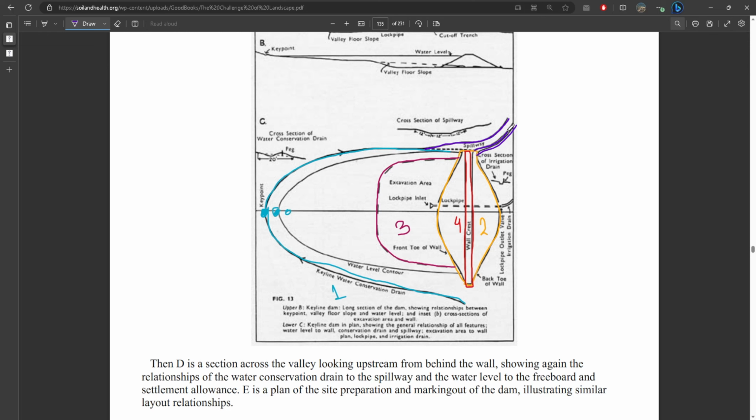So notice that there is an embankment extension right here. The reason for this is that you can release the outflow somewhere where it's safe, where the slope is kind of flatter, so that you can protect this side of the embankment, right? If you release the flow right here, it may start rubbing against the embankment and eroding it over time. So what we're going to do instead is try to release that flow somewhere farther away. So maybe somewhere around here.